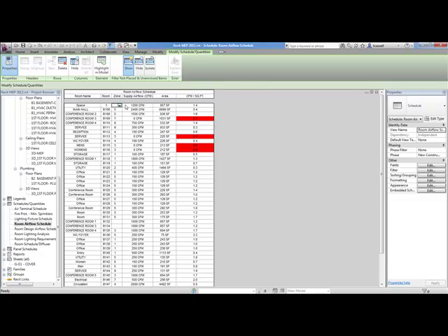So this is the space that I just created. I didn't give it a number yet. It actually belongs to the first floor, so it would end up being 101. This is conference room 6, and I haven't assigned it to a zone yet, but it knows that I put 1200 CFM worth of airflow in there because of the 4 diffusers. It knows the area, and therefore I have a 1.4 CFM per square foot ratio for that room. Now I can decide if that's acceptable.